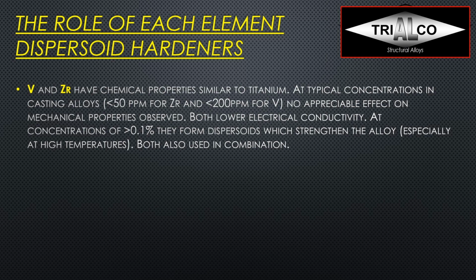Both lower electrical conductivity, and really, if you want them to have an effect of dispersoid hardening and therefore strengthening the alloy, you have to be above 0.1%. I see most alloys using them at 0.14, 0.15%.